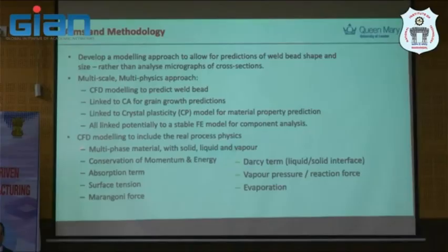And then in order to do this CFD, we need to include the real physical phenomena. I didn't mention this explicitly in the previous talk, but it's probably a good time now: we have a multi-phase material with solid, liquid, vapor phases. But in the simulation I'm about to show you now, it is just a two-phase problem. Two-phase means the metal phase and then the gaseous phase. We will talk about this later.